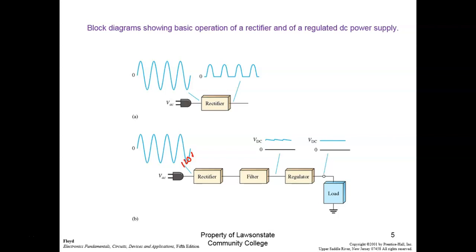So when we design this thing, we're going to try to design it around what? A change in input. Alabama Power says plus or minus 10%. So you could literally have 12 volts up and 12 volts down and it would still be considered legal. So that's what I would design around. I would design around what your power company guarantees, right? Understand? And if it gets out of those limits, it gets out of those limits.